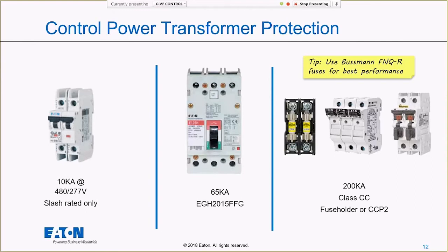Also, whenever you have fuses in front of transformers, you have a lot of options on what that fuse goes into. A lot of times you can get that open holder, the first one shown there, that mounts right on top of the transformer. A lot of people love to use that. You put that right on top of the transformer, you take up no extra space in your panel. That is absolutely fine if you want to use one like that.